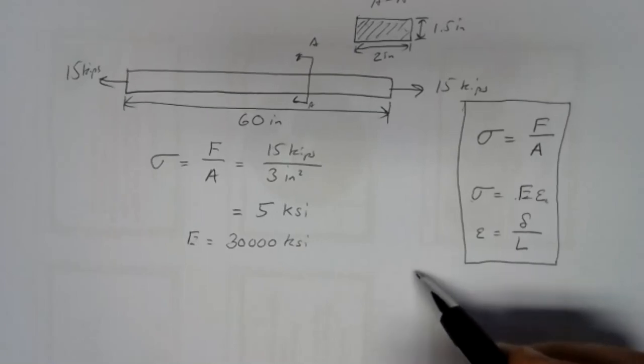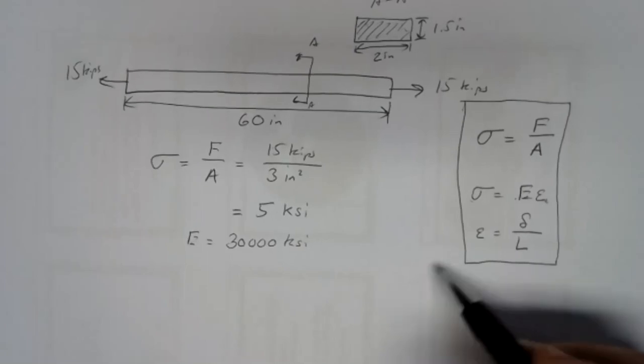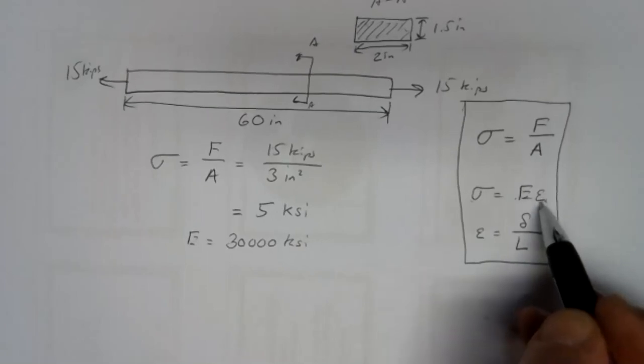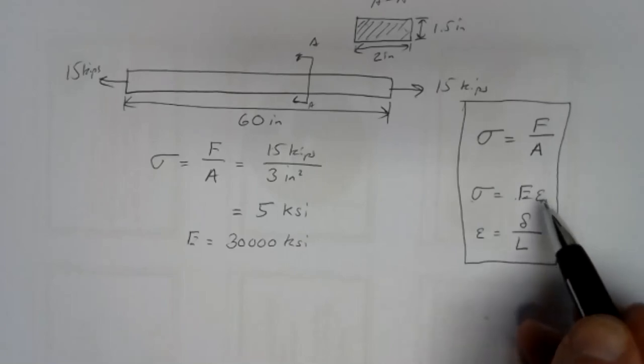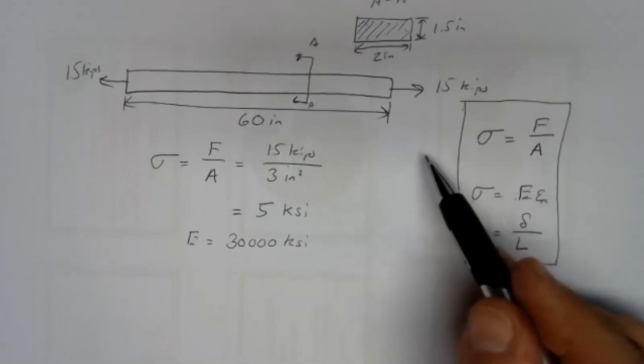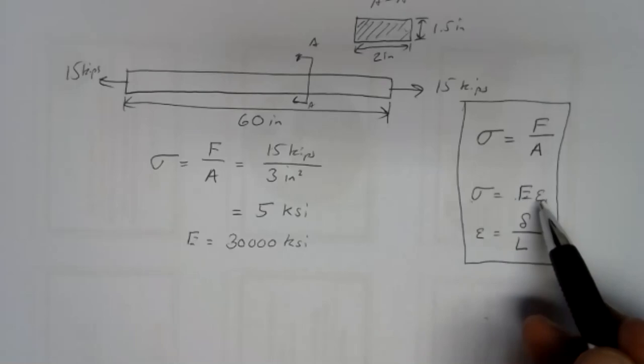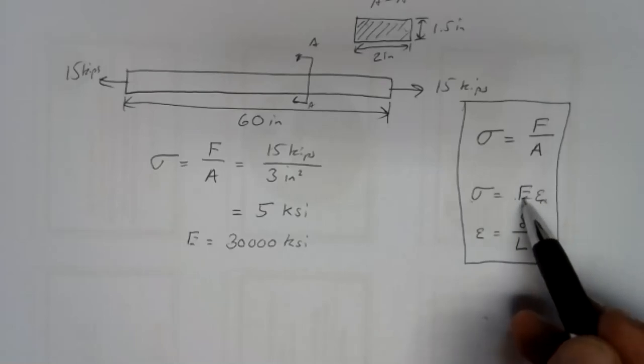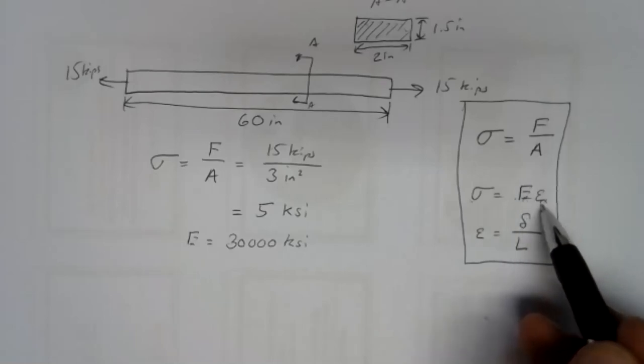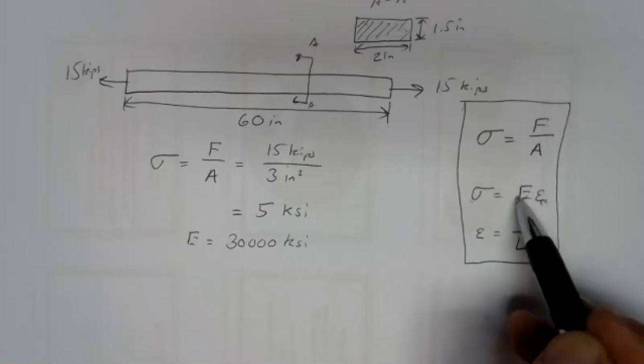Essentially, you can think of Young's modulus as the amount of stress you'd need to get each inch to grow by 1 inch, if that was physically possible. Now, you'd need more stress than the ultimate stress to get that to happen, but that's one way to capture how large the Young's modulus is: to get strain to be 1 inch per inch, so each inch grows by another inch, it doubles in size, you would need Young's modulus as your stress.